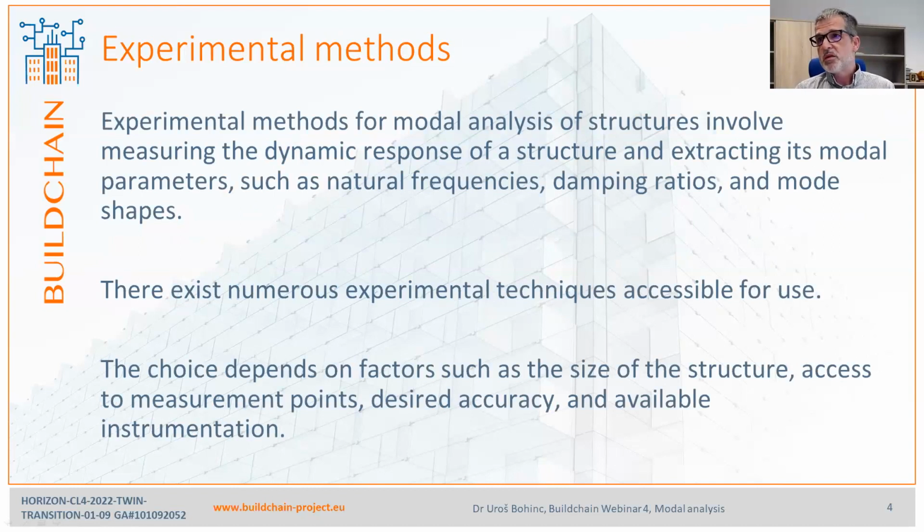Experimental methods, techniques. There are many of them which can be used. Basically, they can be divided into big classes. One of the classes are experimental methods which use artificial and controlled excitation of a structure. So we have to excite the vibration of a structure and then measure the response.